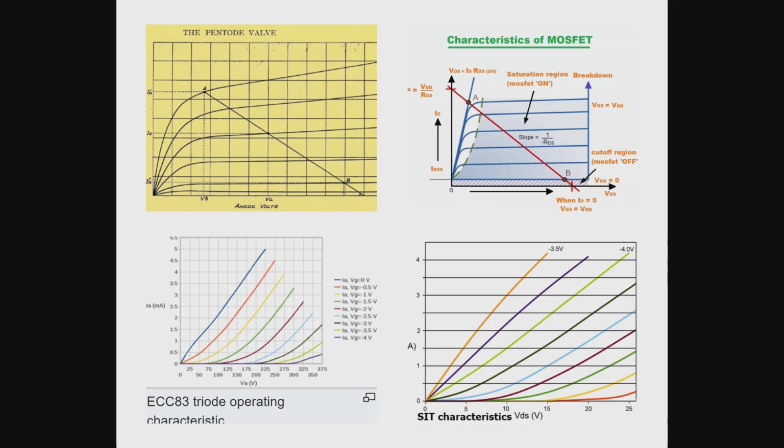Conclusion: JFETs and SITs do not aim to switch. They aim to regulate. They behave like a voltage-controlled variable resistor, or a potentiometer, with the crucial difference that there is no mechanical contact, no wear, and no contact noise. The regulation is performed purely by voltage, fully contactless. This is what gives these devices their triode-like character. And this is also why they were so special in audio applications, even though, on an industrial scale, they could not compete with MOSFET technology.